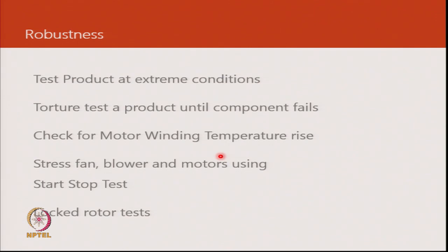We also take components. So, let us say the motor, what happens to the motor? The motor has to withstand a certain life as a part of the unit. It again goes through torture test, start, stop, and the winding temperature rise is measured, and if it is not complying, we need to redesign the motor. And there are several things to do there. You can change the class of insulation of the motor, you can change the way the motor is being cooled, the windings, and not all of it as a designer you need to get into, but you need to connect with the supplier who will give you back a modified sample which will meet and comply.